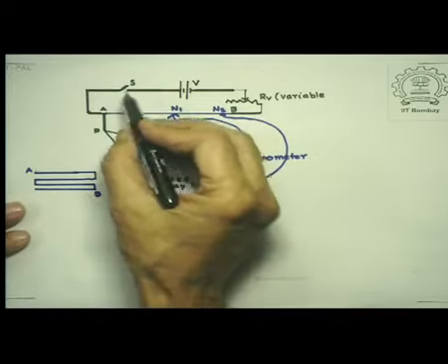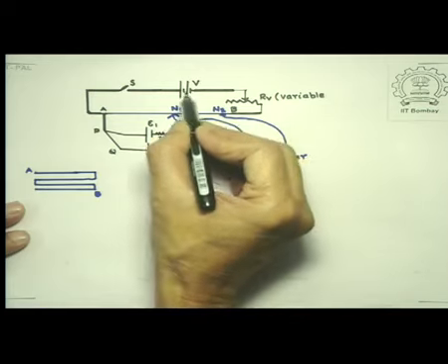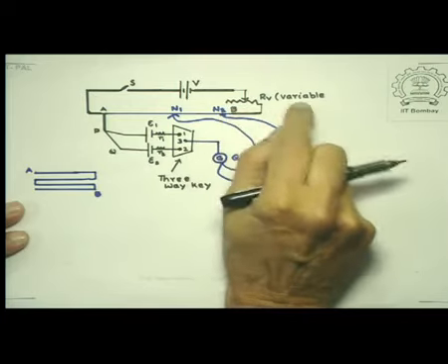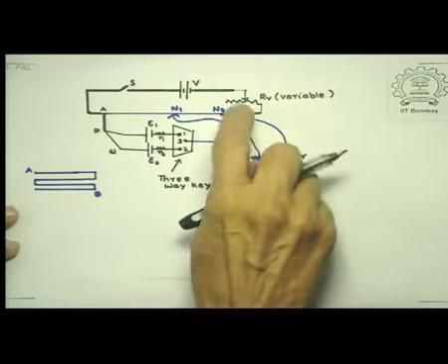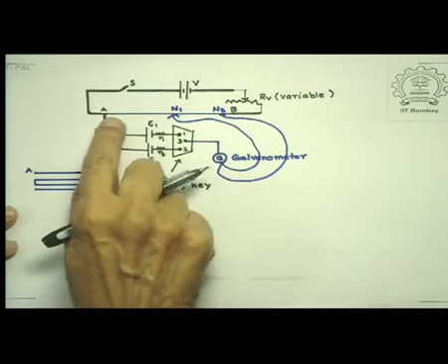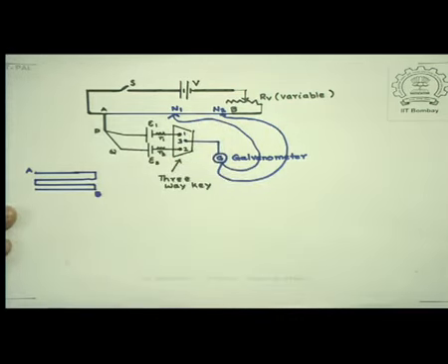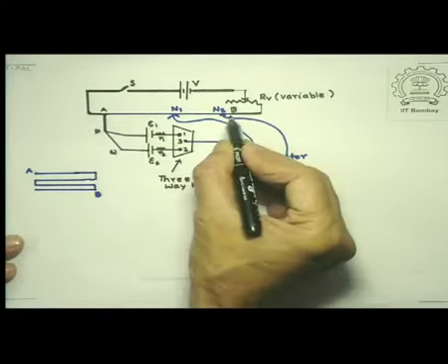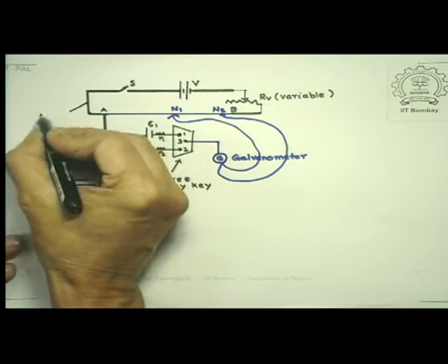So there is this main circuit with a source of voltage V, and there is a variable resistance here which is varied so that the deflection of the galvanometer at the two ends comes within the range of the galvanometer. There is a switch which can be closed, thereby enabling the source V to send a constant current through the circuit. Now what happens is this, that this part AB, these are all resistanceless wires.